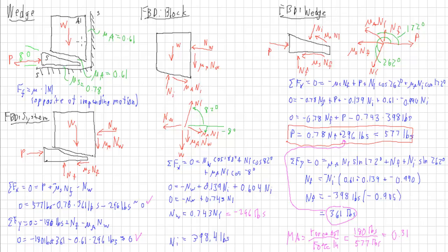Another reason is that this situation is self-locking. In other words, you might push it in, but because of the angle, is the weight going to just come down and slide it right back out? You want to make sure that if you want to keep it in position, that that's not going to happen, that the friction available is going to keep it in place.